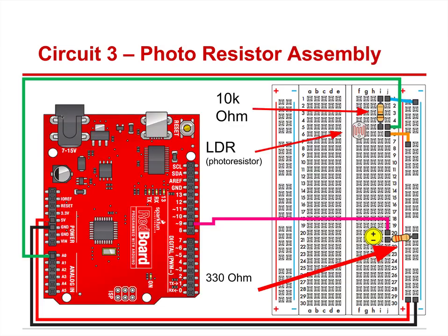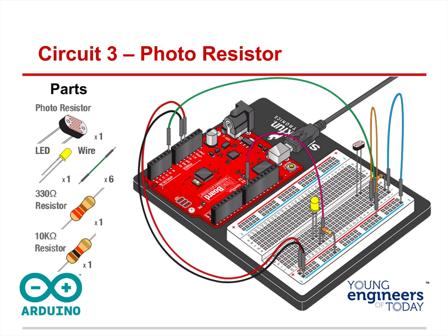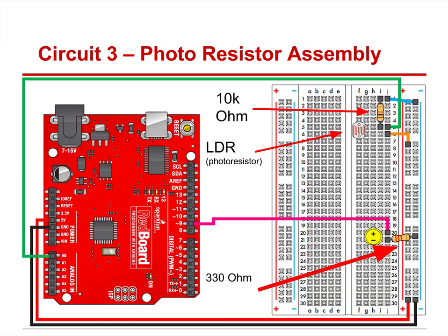The photoresistor has a little bit of a copper wire right up on this line here. You'll see it right there. We have a 330K, and then this black one is a 10K. Important not to get those backwards. All right, I'm going to show you the screen. You're going to pause this and put this together. If you do not have a breadboard or an Arduino and breadboard electronics, think of using 123D Circuits by Autodesk. It's free. It'll allow you to simulate this.